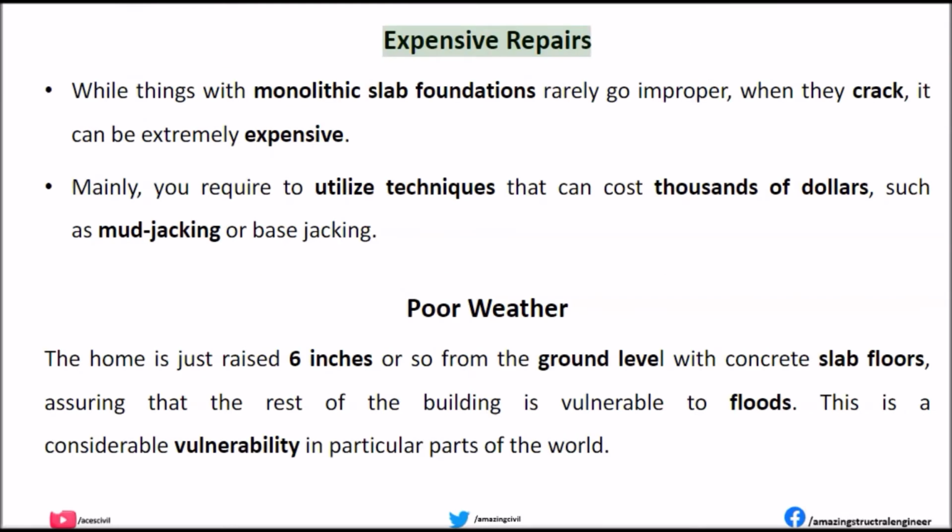Expensive repairs. While things with monolithic slab foundations rarely go wrong, when they crack, it can be extremely expensive. Mainly, you need to use techniques that can cost thousands of dollars, such as mud jacking or base jacking.